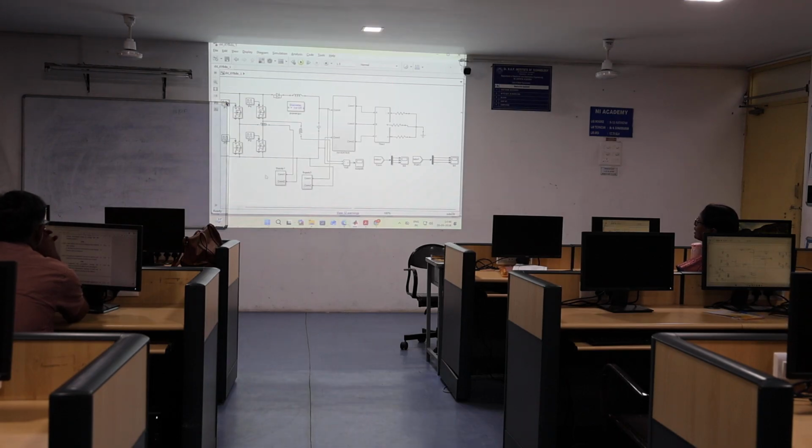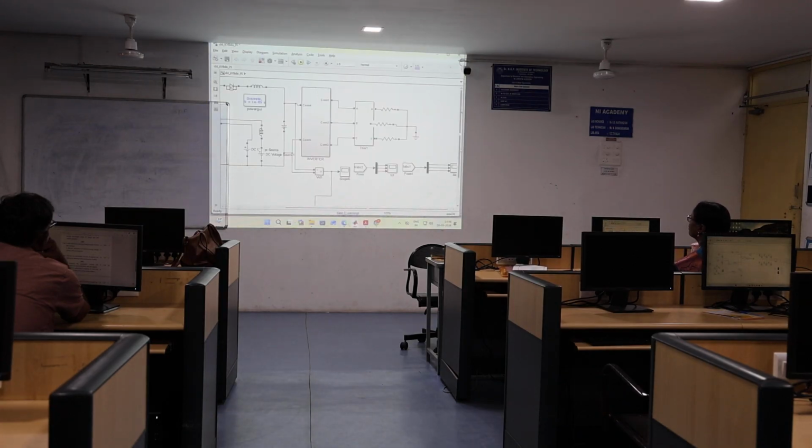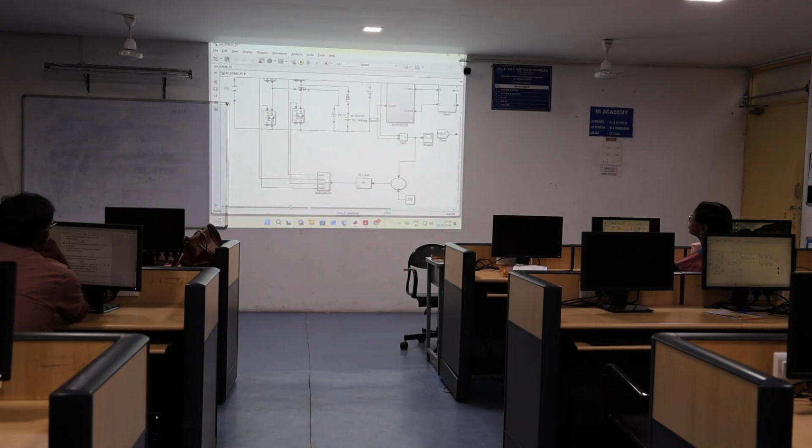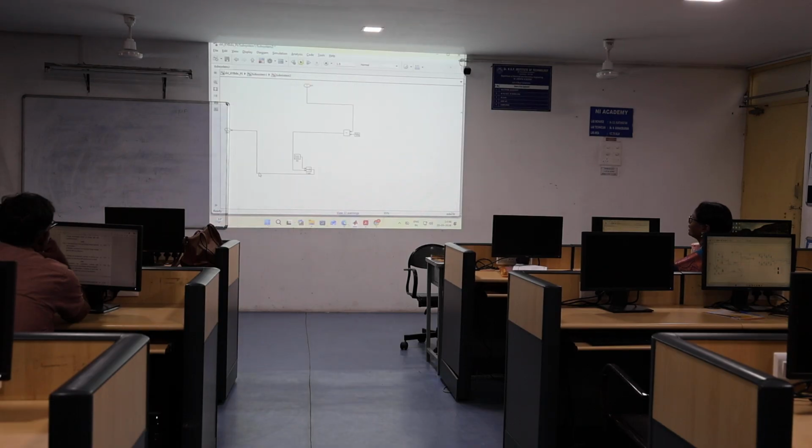So this condition is about a non-linear source. Why did we give this non-linear source? We can't assume that when I go with any kind of input like renewable energy, it will be a constant input. So for that we always work with variable sources. Here we are giving a PI controller, with the PI values and all. And again, one is the repeating sequence and another is the other input. According to the AND logic, this will always be enabled. Only whenever this sequence is enabled will it be fed to the switches.